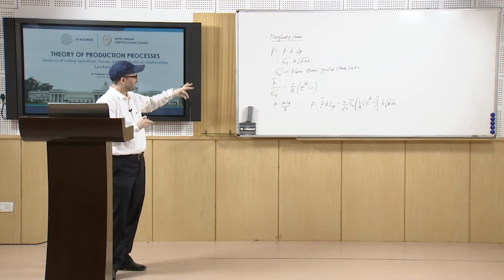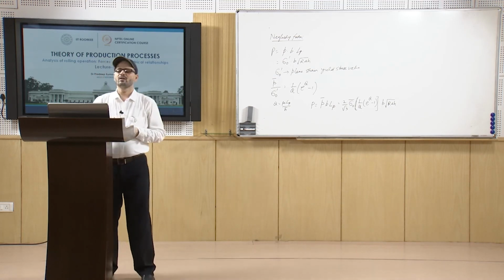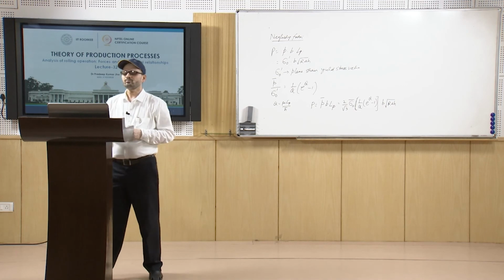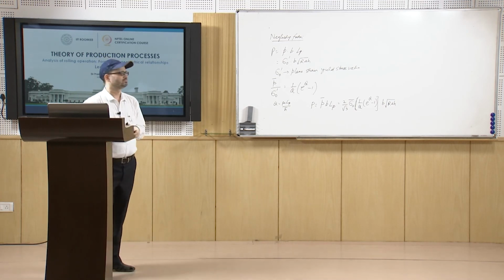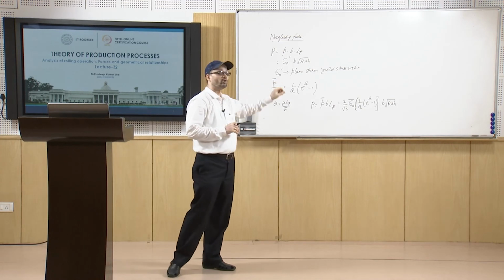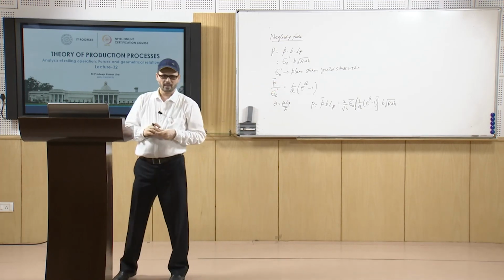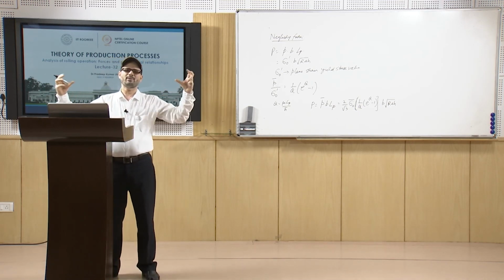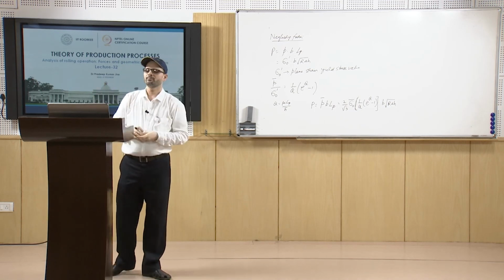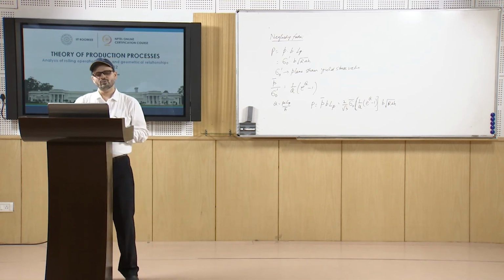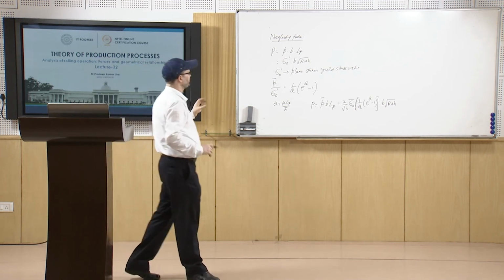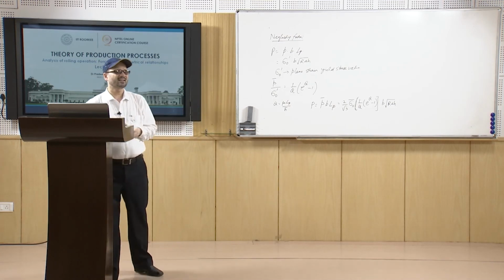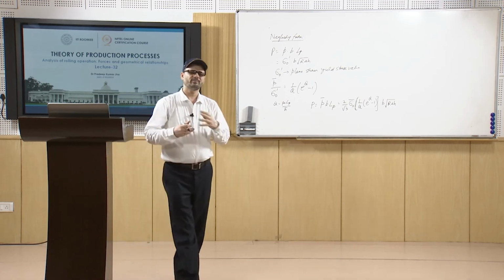Both roll load and length of arc are important for the calculation of the roll load, and smaller diameter rolls are more effective, but they need to be stiffened, and that is how you apply the backup rolls to do the rolling operations. So, there is certainly a minimum gauge sheet which can be rolled. There is a limit, and that is how the rolling operation has to be carried out.